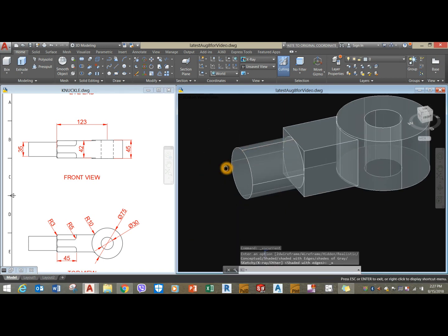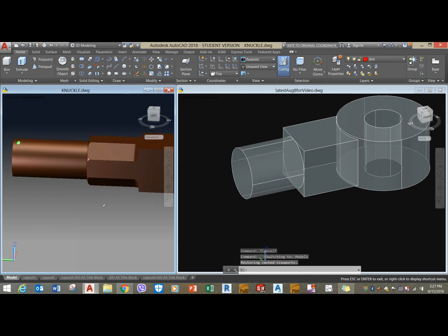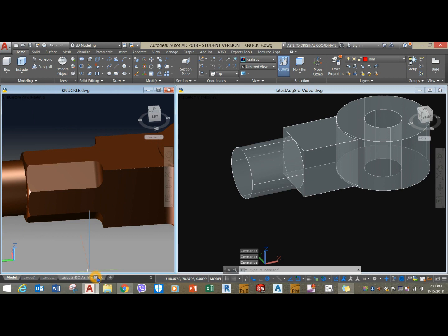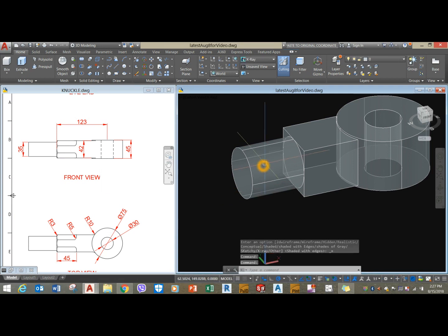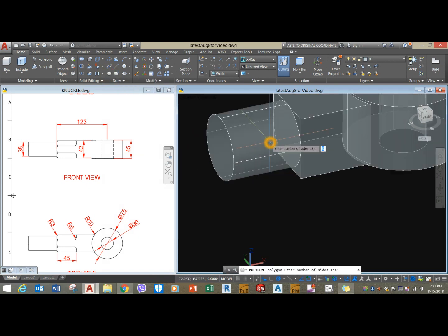X-ray. Now what I'm gonna do, create this smooth edge here. So in order to do that design, create an octagon and extrude it towards the center and use intersect command. Select polygon from the ribbon, enter 8 sides, type 8 and enter, and then locate the center and inscribe in the circle. I'm just gonna enter 21 for radius.